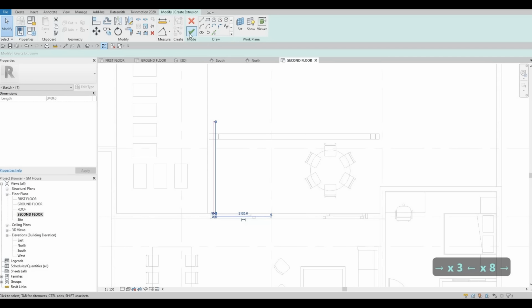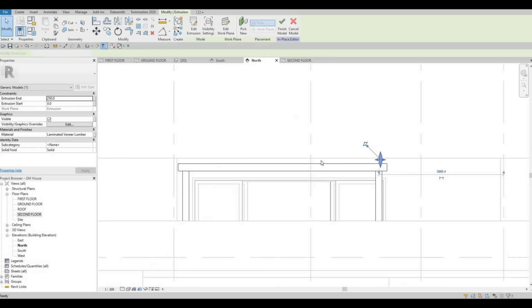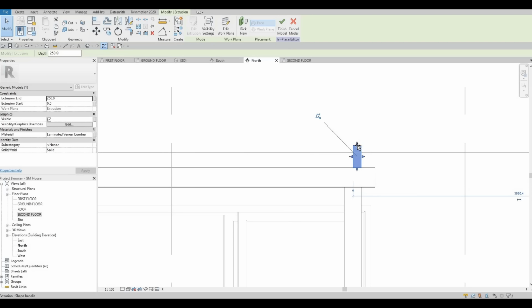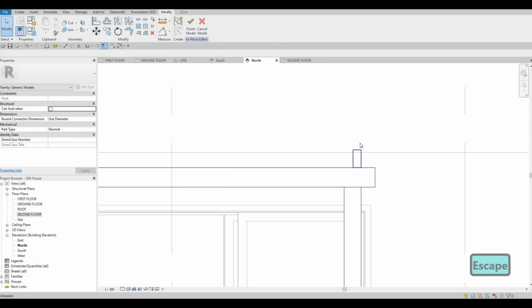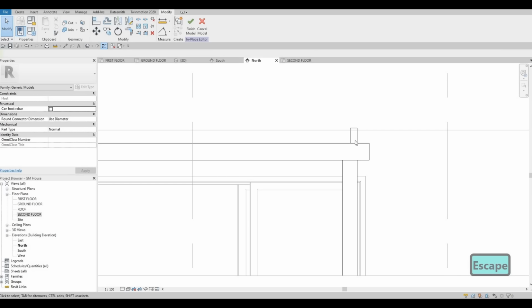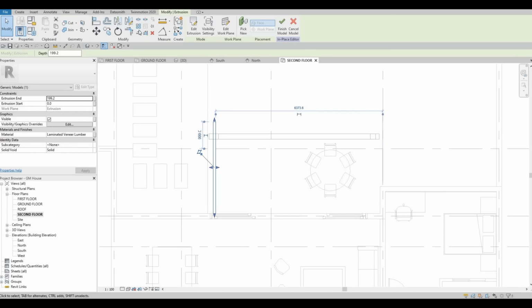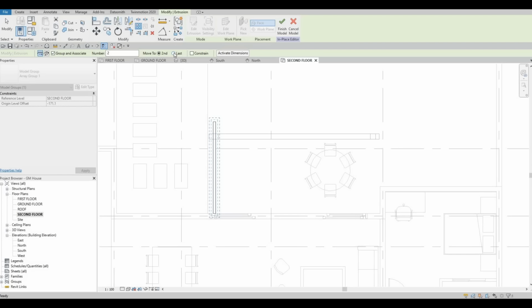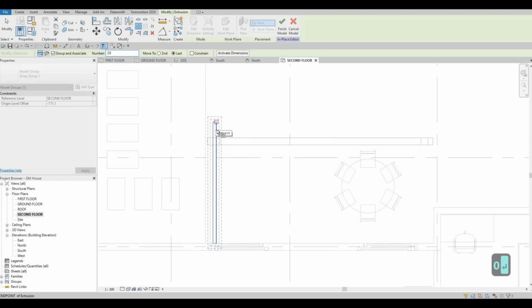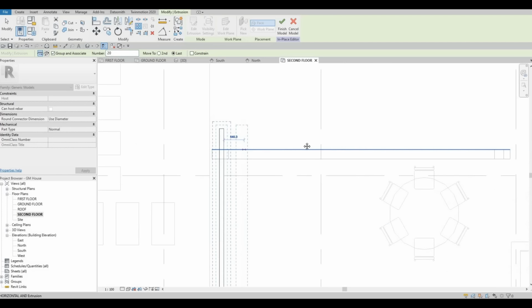And then here we could click on finish, but we need to clean it up so that it's not too high. So that's perfect enough. I like the height and the thickness. And then let's go back to second floor, select that, and then we could array, and then you need to choose last and then how many you want. So I'm just going to estimate probably 20, and then grab it, and then we want to stick it at the last.